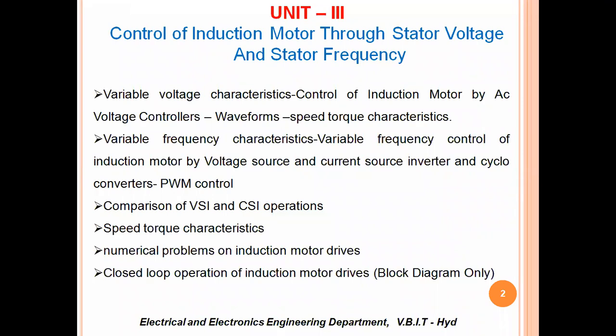And not only that, these brushes and commutators definitely require frequent maintenance, and these cannot be adopted for explosive types of applications like petrol wells or diesel wells or any other flammable things. In those applications, we cannot adopt DC drives. Because of the brushes, we will get sparks. So those are not suitable in those types of applications.